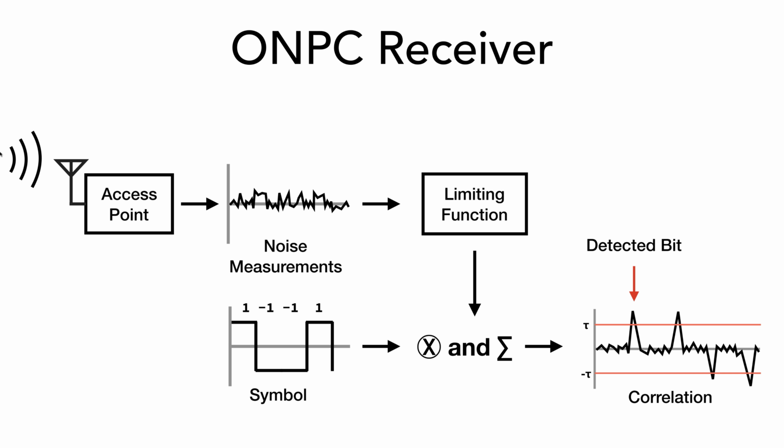One thing I did want to mention is here these noise measurements. You might be wondering, why do the noise measurements look like that? I just drew it kind of as pretend, but the reason why the noise measurements aren't very clean is because there are other interferers going on, other transmitters. There's what they call the noise floor, just the kind of noise that exists in the world from thermal noise and from other things.